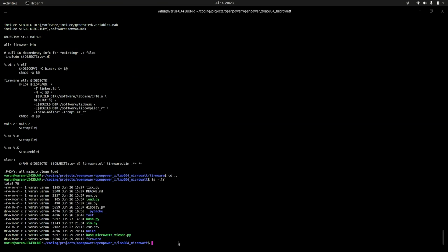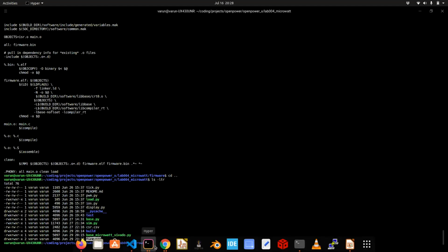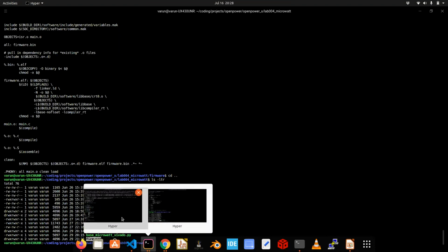This is the basic structure of a project using LiteX. You will have the build directory, which will contain the generated bitstream as well as the auto-generated header files and driver C programs. Then you can write your own firmware, and you can include and pull in those header files, and access those peripherals. Let's see what's happening here.